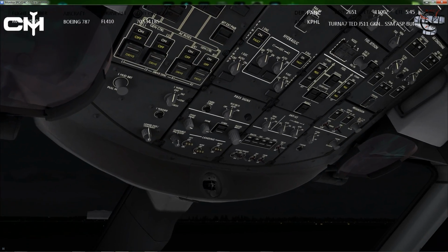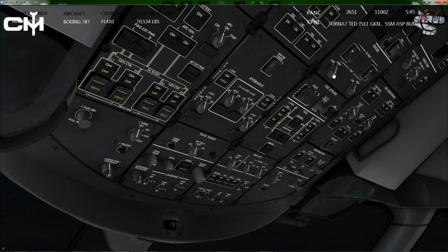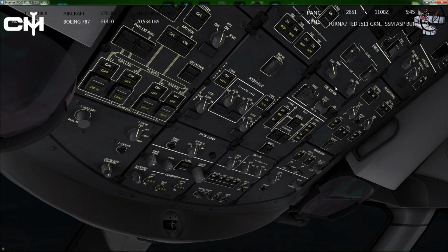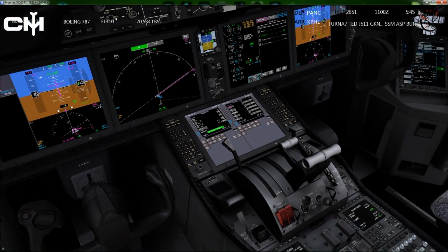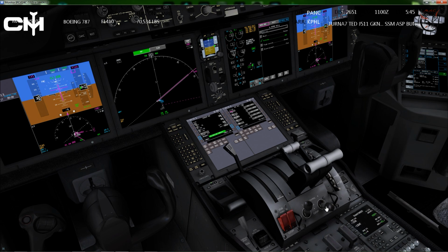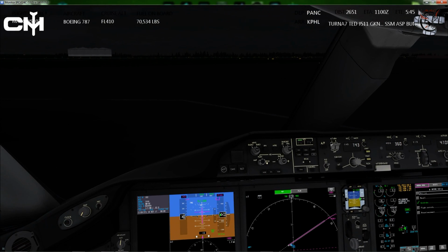So, let's go ahead and start the engines. All the way up top here, the engine start switches. Clear to start engines. Roger. Clear to start engines. Okay. Start both engines. So, left click to start. Count to 5 in your head, which I'm not really counting, I'm just guessing. And then click the other switch to start over here. And then come down, fuel control on, and just because I like to keep it even, fuel control on after about 5 seconds. And both, oh, it's turning the nose the wrong way, isn't it?